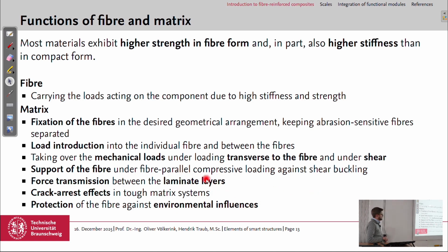And fiber reinforced plastics are often laminated from different layers, which are stacked on top of each other, and the matrix acts also as a force transmission between these layers. And if you have a tough matrix system with some thermoplastic parts in it, then it also can act as a crack arrest. And you also protect the fibers against environmental influences, UV light, chemicals, and so on.